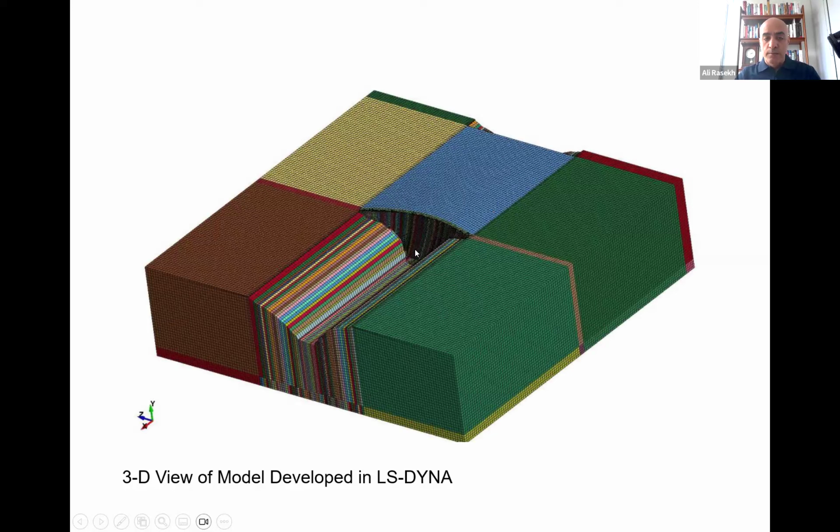So there's a dam, and a reservoir representation. On one side, we sometimes emphasize that this is compressible, because sometimes we use only added mass to represent the seismic response of water. And a good, nice, large representation of foundation.